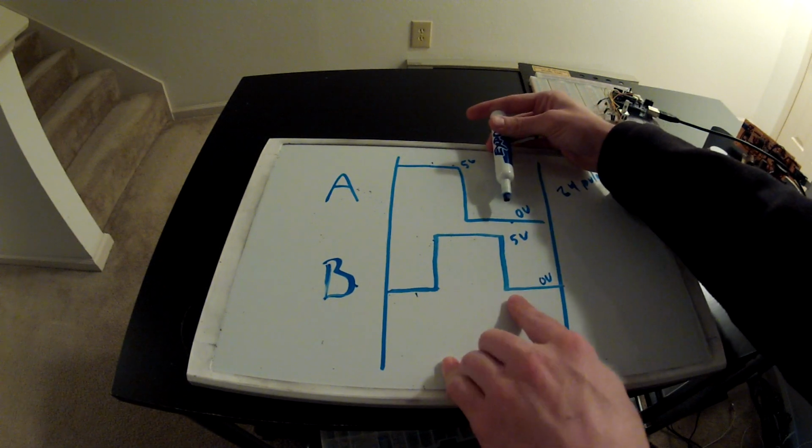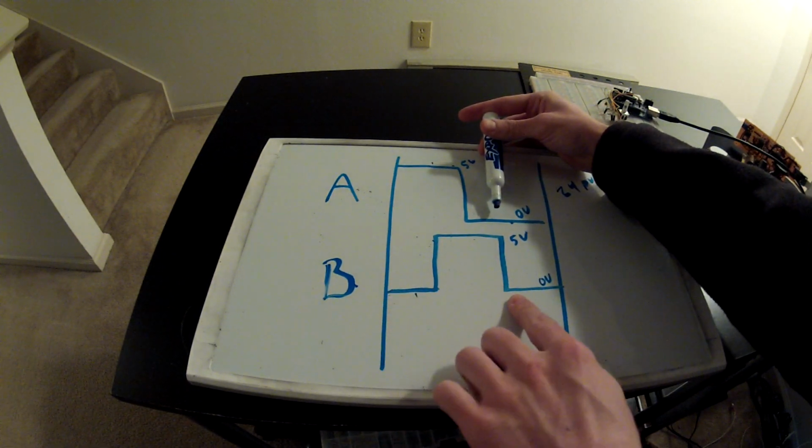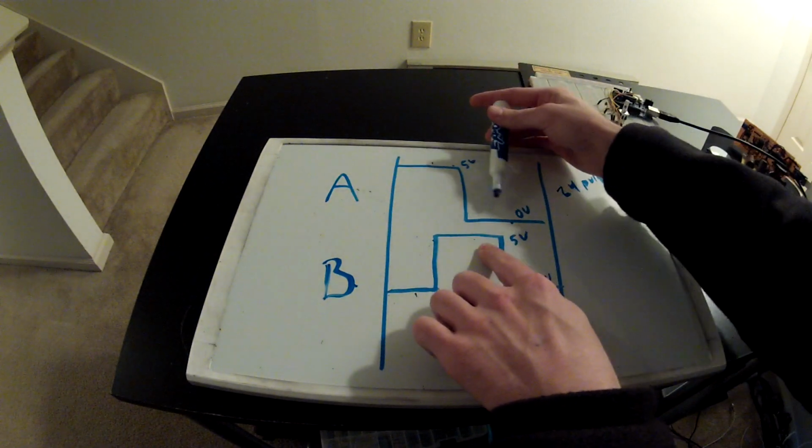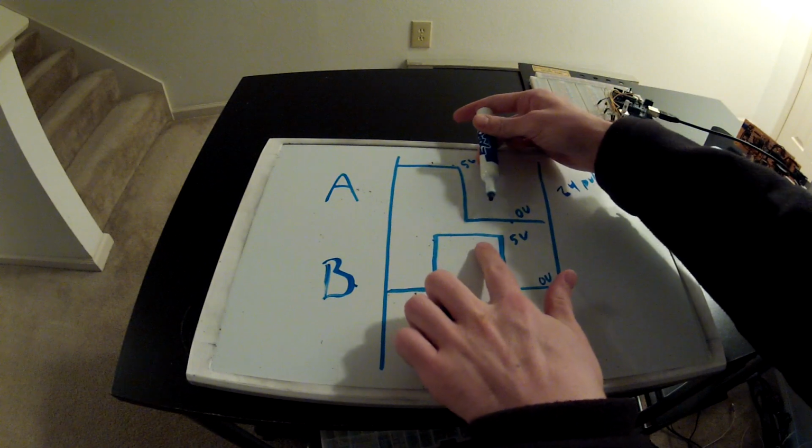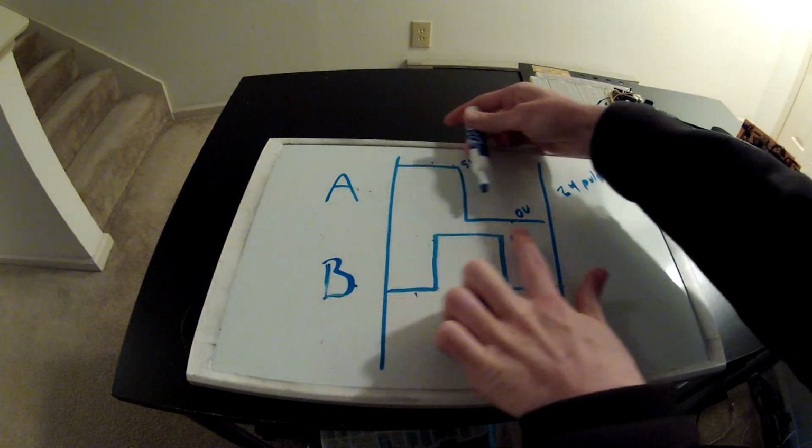You get a change in the state from the B signal from low to high while the A signal is still low. That means you're moving reverse. So it's the same exact thing. You just keep going through it. You just move in time.